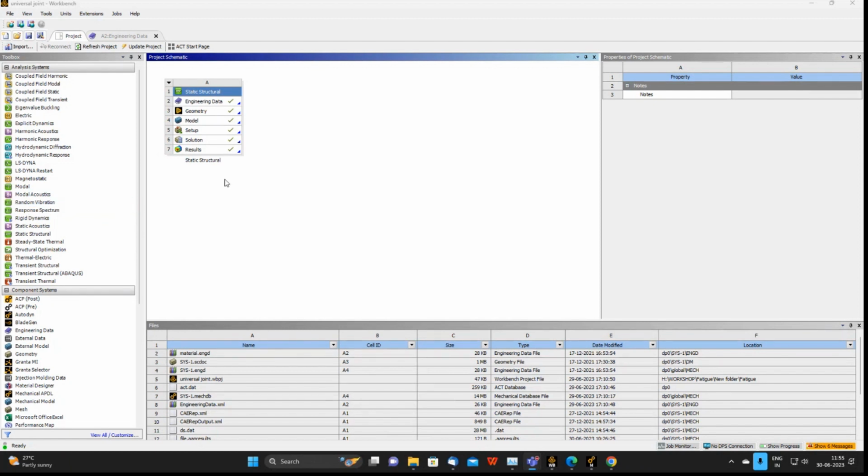And in some cases, due to the friction, there is a generation of heat between the components. In that case, we are going to use this coupled field transient analysis. There we are merging the transient structural part with the thermal part. There we can perform the fatigue life.